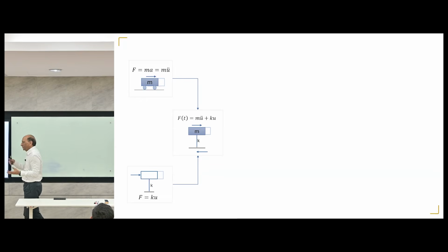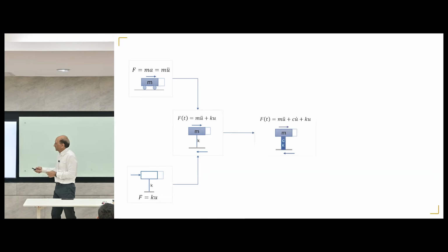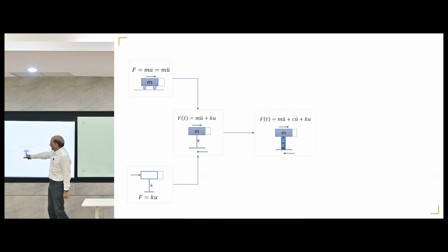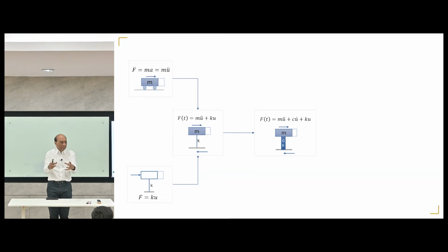The damping is a property that the structure with molecules will change, the density will change, and heat will be generated when it moves. So all of that now comes in because that will also add another force into the system. So that means we go and we say, okay, now damping is also part of the column. Column is not a stick, column is real material. And when it deforms, it will have internal heat generation and internal change in its molecular compaction and so on and so forth. So the damping also comes in from the material of the structure and other things.